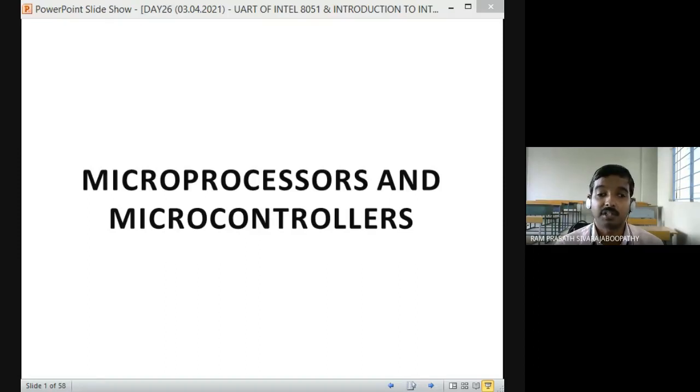What are the different operating modes of timer or counter? What are the different modes of operation? Yes, mode 0, mode 1, mode 2, mode 3. We have to know the description of the modes also. Mode 0 means 13-bit timer or counter. Mode 1 means 16-bit timer or counter. Mode 2 means 8-bit timer with auto reload. Mode 3 means split timer.